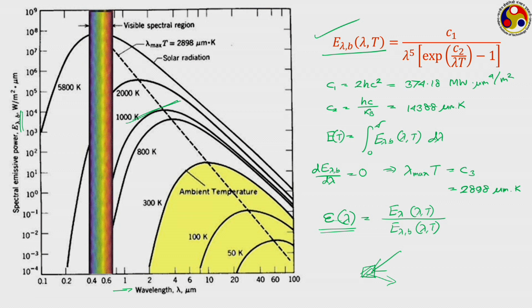After some time it will reach an equilibrium temperature, under which condition the emission coming from the source and the emission going out of this particular body should be equal to each other, so that the temperature is maintained constant. Then, applying an energy balance, we can easily sense the temperature of this particular source, as we are continuously measuring the temperature of this particular body using any of the methods that we talked about till now, like thermistors.